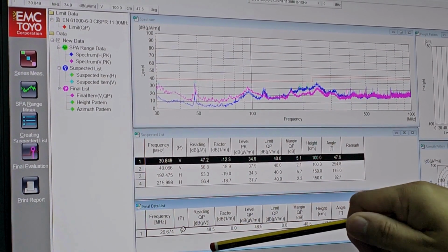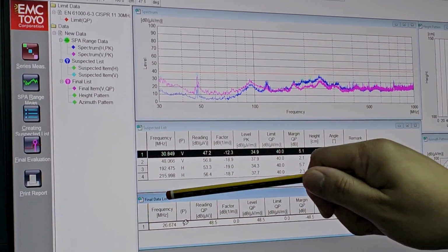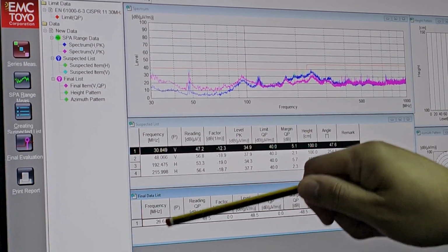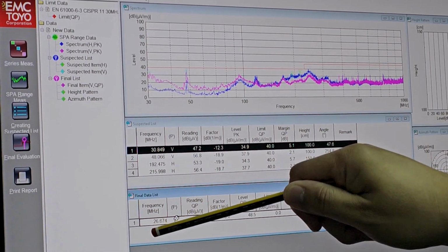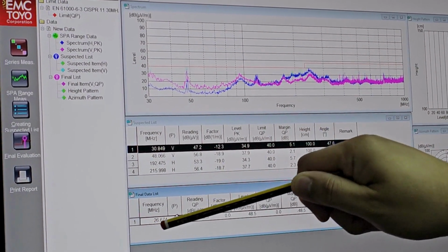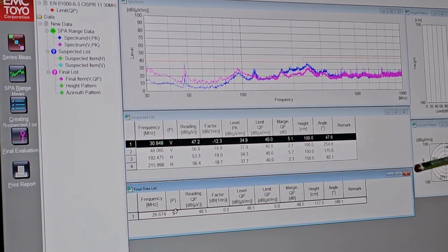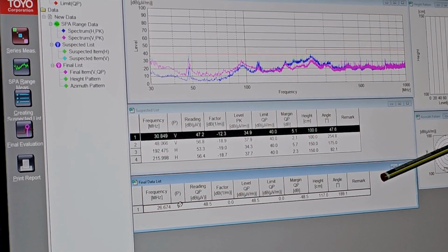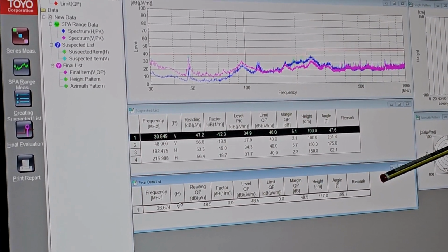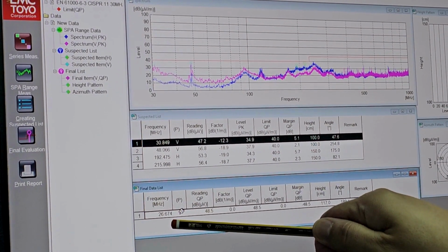But over here you have some idea of how the radiated emission test is done. Because the frequency is lower than the criteria of 30 megahertz to 6 gigahertz, and over here it is much lower than 30 megahertz, I guess the manufacturer of the laptop probably certified it as passed, because this is well below the frequency of test for RE.